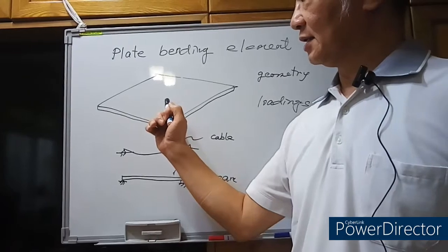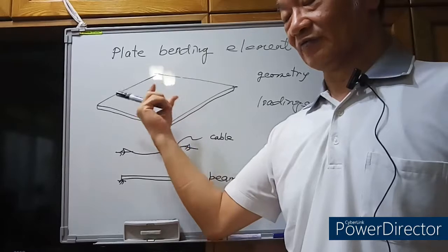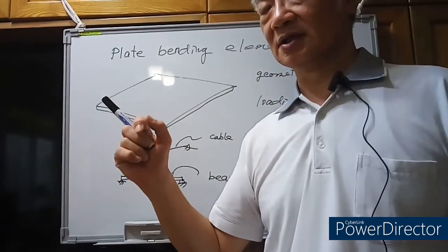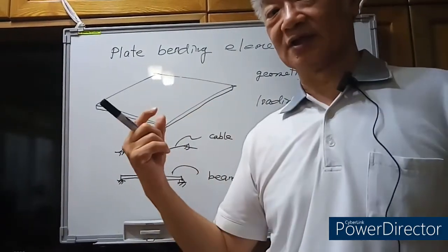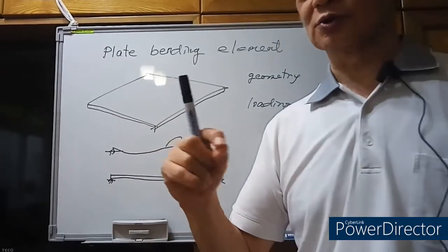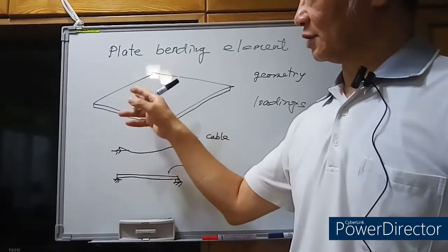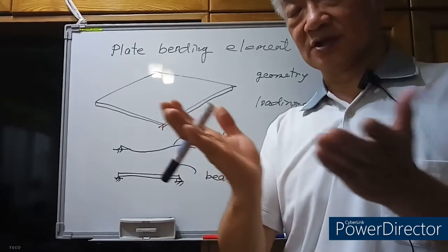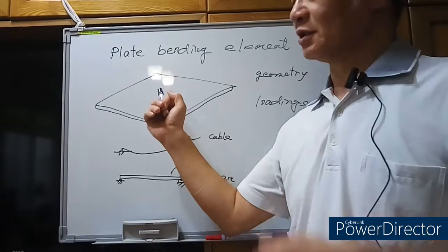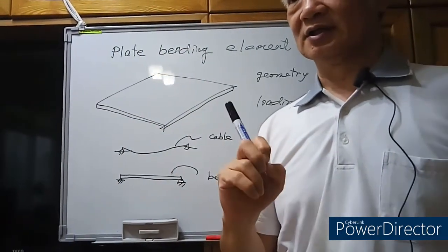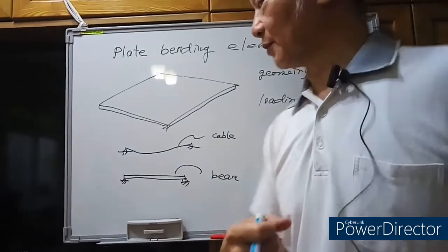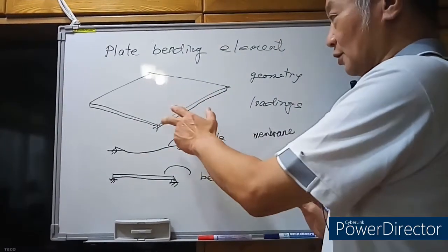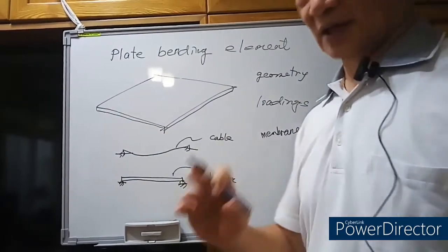For the two-dimensional case, if we have two major dimensions for the plate problems and we consider only the axial force, then we have the so-called membrane model. In the membrane model, along the two major dimensions, the bending stiffness is close to zero. Then only the internal axial force will be considered, which can be used to resist vertically applied loadings. Such a structural model is the membrane model. Okay, so you can say the membrane model is the two-dimensional cable model.